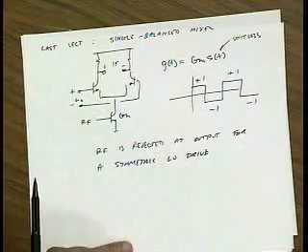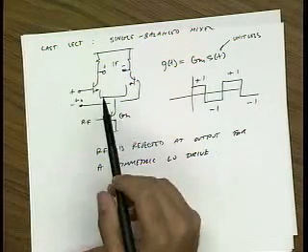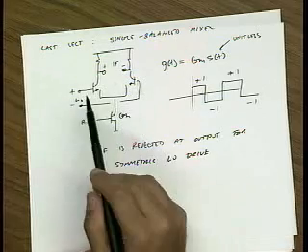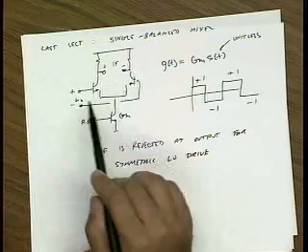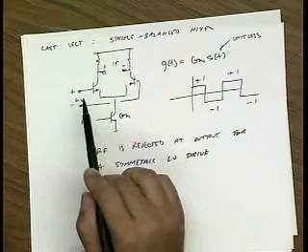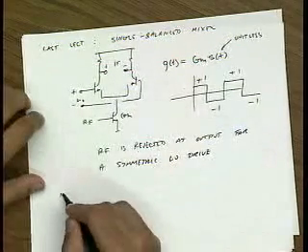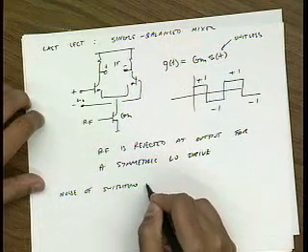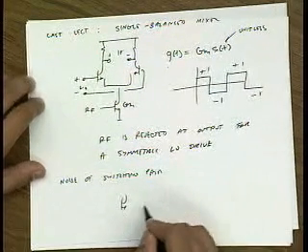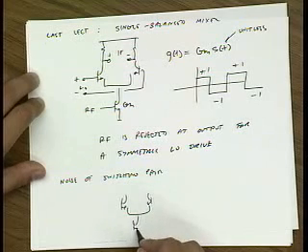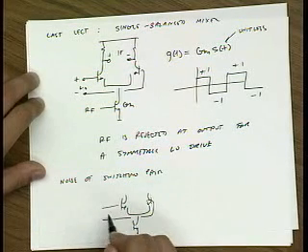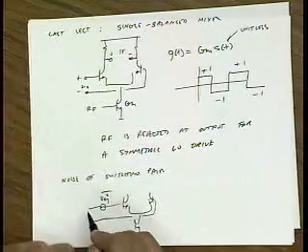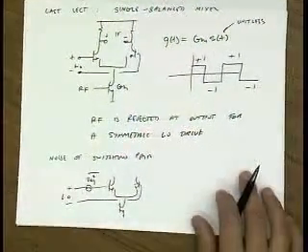There's another factor that comes into play that actually dominates, and that's the noise of this switching pair itself, right? The switching pair, this is not a noiseless differential pair. It has noise in it, right? So the equivalent circuit is as follows. Basically, there's a noise, V equivalent, in series with our LO.